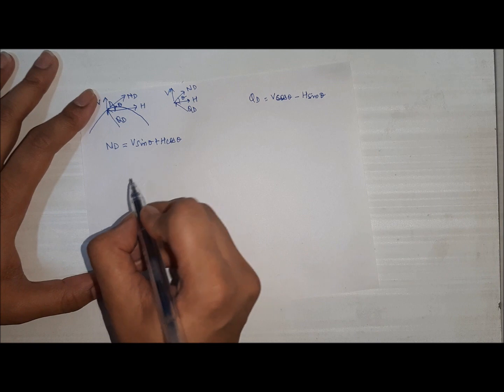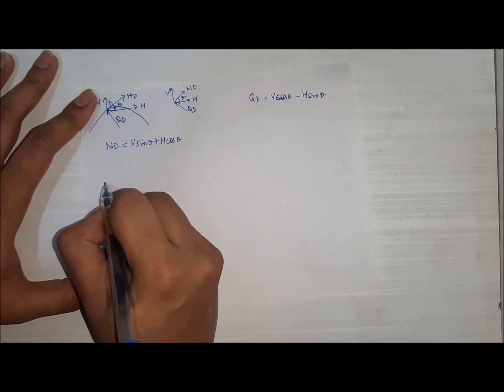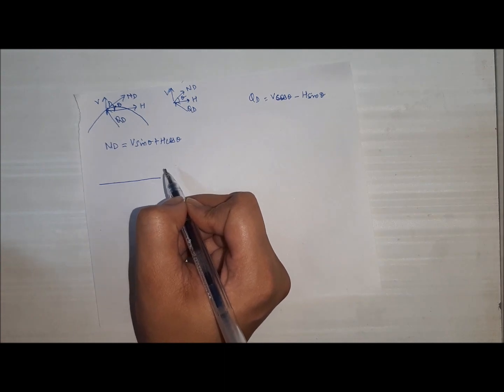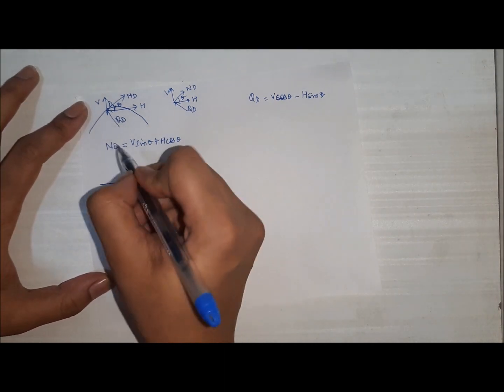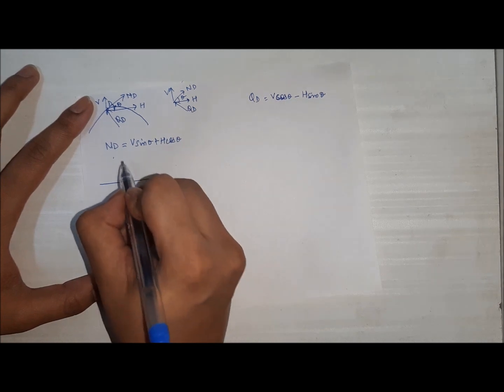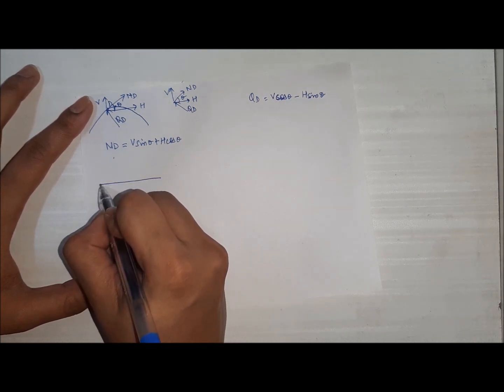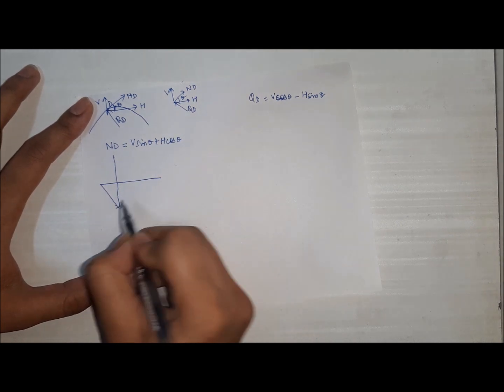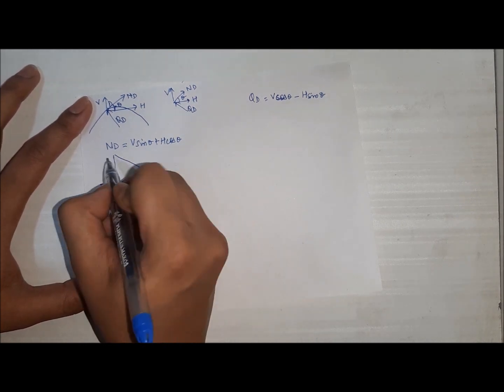Now for plotting the figure, V sin theta and H cos theta. V is nothing else but the shear forces or the reactions. So for shear force at point D, as we had seen in the beam cases, simply supported beam part, this will be the figure for ILD of shear force.